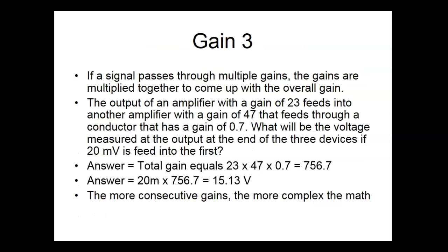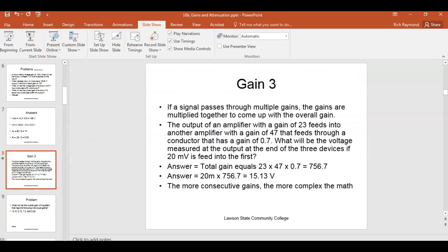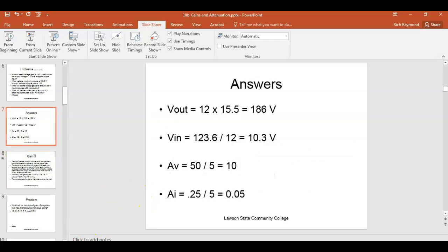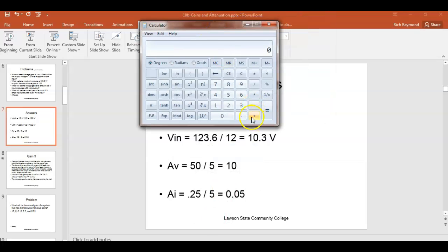So half power is considered to be the bandwidth of a system, right? You have the maximum power, and as soon as it drops down to half power, that's what we call the bandwidth. It's between the 50% power points. If I take the log of 0.5, right, you understand, it's minus 3 dB. So 3 dB is the half power point.